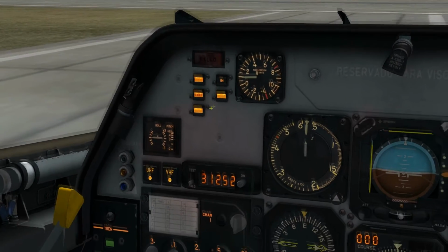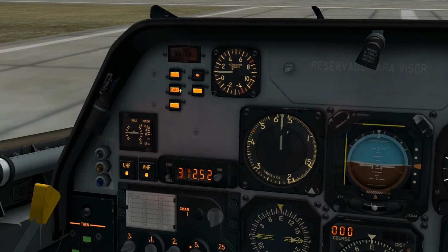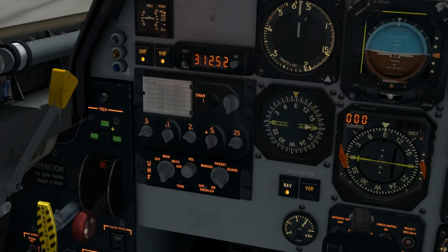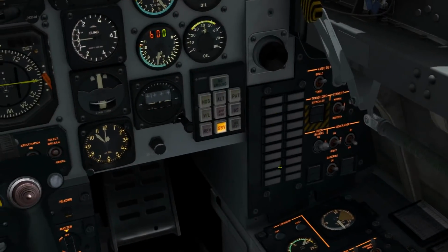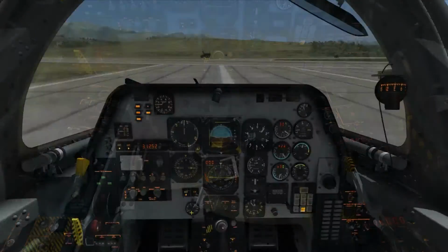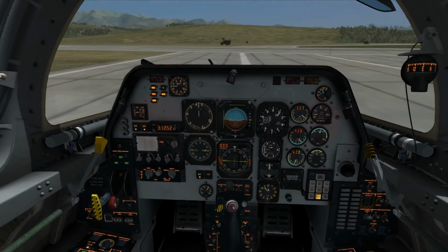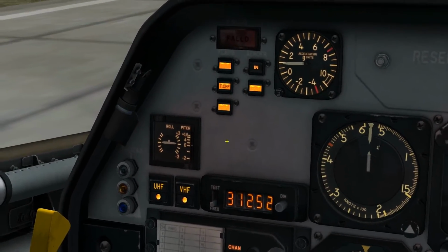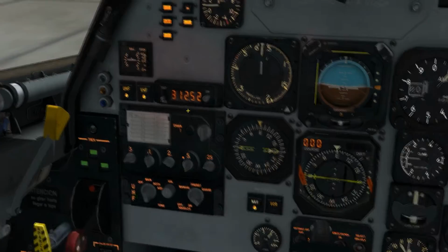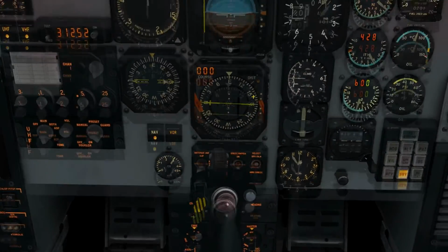Air brake, check in. Flaps, check takeoff. Landing gear, check 3 green. Warnings panel, no lights. Harness, check. Well, we are supposed to have the harness adjusted. Trims, we cannot check it, but when the indicator will be operable in the final version, we must check that vertical trim is marked to do minus 1.5 and 0 degrees on roll axis. Okay, that's the end of the taxi checklist.